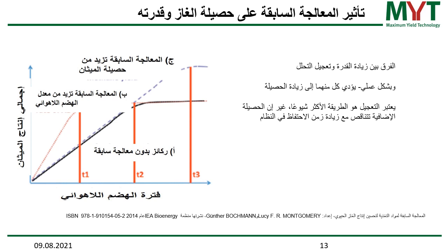The gas yield is actually the amount of gas you achieve in a technical process. A technical process has only a defined retention time, and it has some limitations in mixing. So you will never get all the substrate converted in a technical process. That's why the yield is always smaller than the potential. And then the third thing which comes into play is the velocity, or the rate at which this gas yield can be achieved in a technical process.